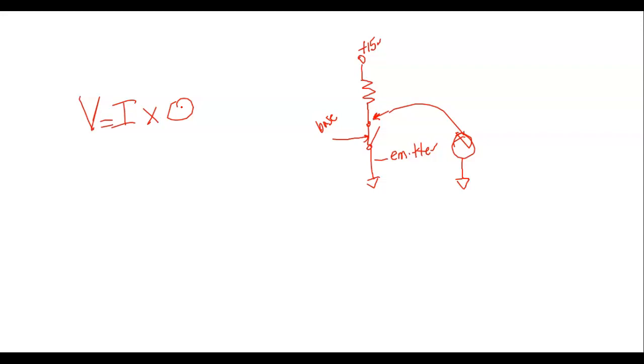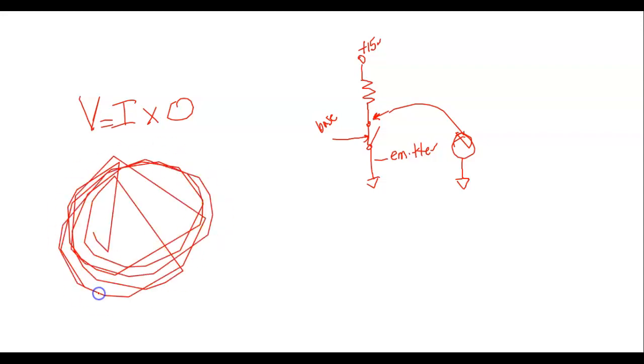0. So if I went to these light switches with all these lights turned on and put my voltmeter across those switches, what would it measure? It would measure 0 volts. And this gets a lot of people killed, right? You'll say, well, let's see if there's power. I need to change my switch out. They get their meter out, put it across the switch, and it measures 0 volts because the switch is closed, right? And how much voltage should be across them when it's open?